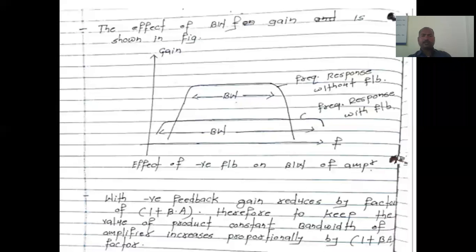See, we have to discuss the effect of bandwidth and gain. In this case, we have discussed what you mean by bandwidth. This indicates the range of frequency, from this to this. If this is 0 hertz, it is with respect to the input, and this indicates 20 kilohertz. So an audio amplifier ranges from 0 hertz to 20 kilohertz.